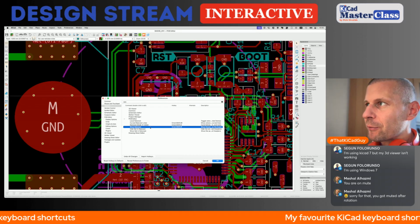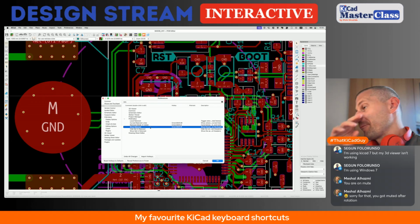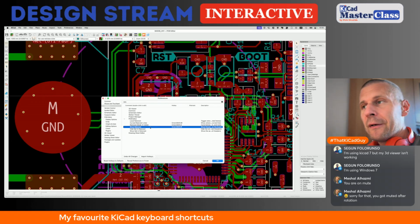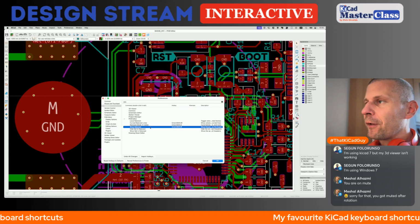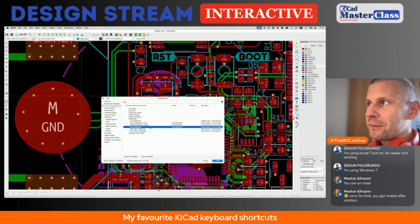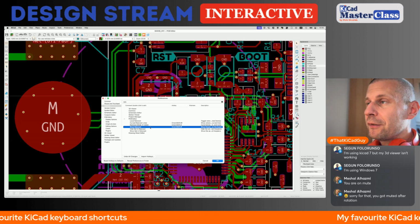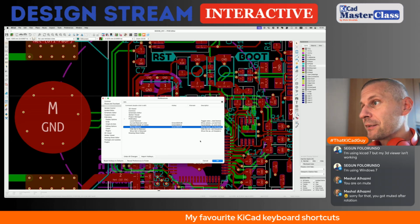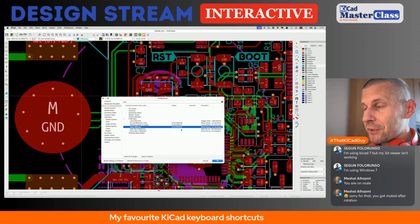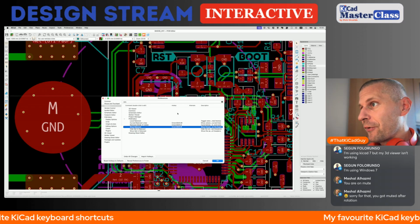When placing components, I sometimes disable showing the ratsnest, because for a rather complex board, there are all the airlines, the white thin lines connecting the footprints, and it's annoying, more than annoying, disturbing. So I sometimes switch off the ratsnest. My setup is Command-Shift-R, but you can define your own.